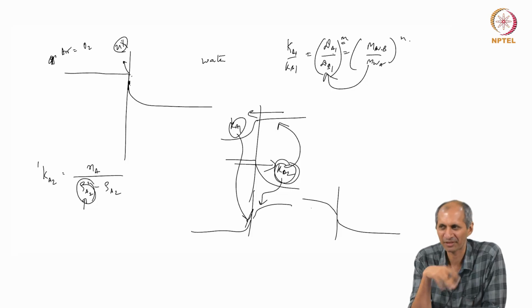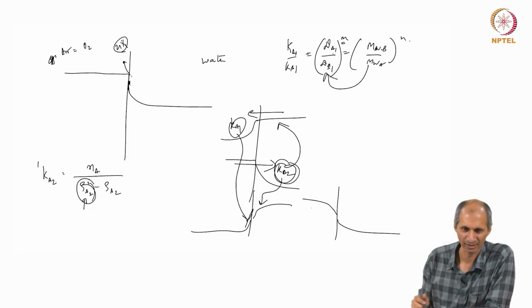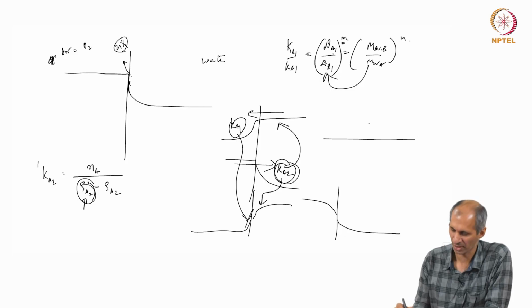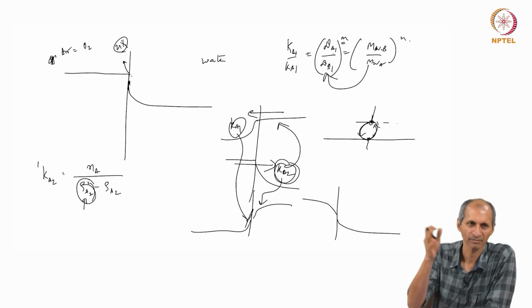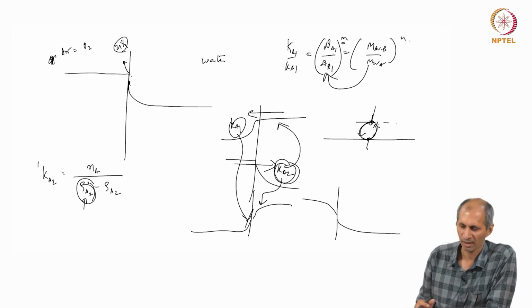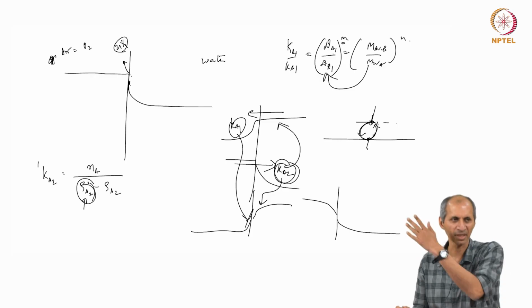What is the definition of the mass transfer coefficients? We are looking at circulation, convection. So, at the interface we are looking at, this is a scale at which this is happening, which is convection plus diffusion. Irrespective of which direction the gradient is, this does not care. This is a hydrodynamic or aerodynamic thing. Whether I introduce a chemical from this side or from this side does not matter. If I put it from here, it will take it here. If I put it from here, it will take it here. So, the convection is happening from place to place. So, whichever side you feed it from, it will take it to the other side.